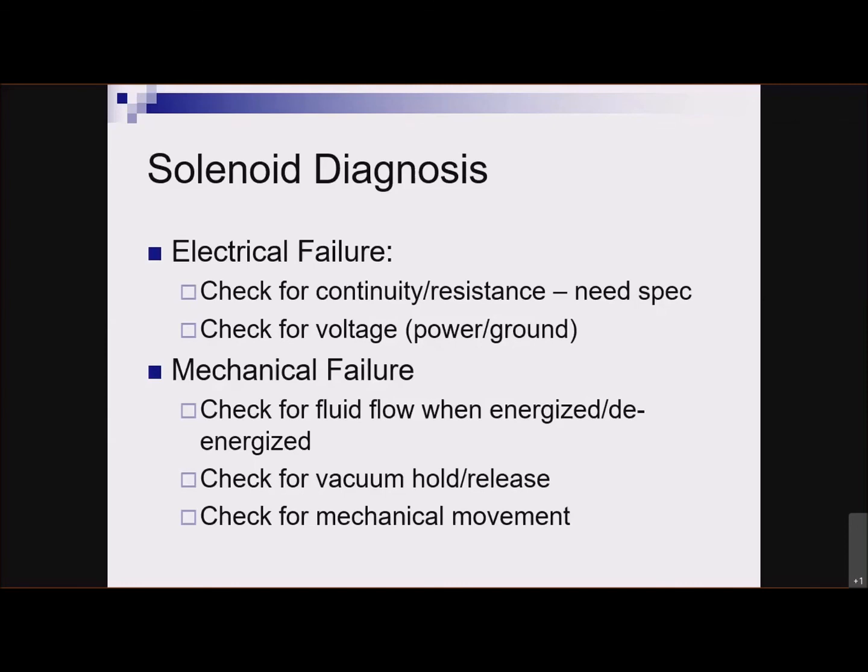As far as mechanical failure, that can be a little more challenging. On a vacuum solenoid, no problem. Blow through it, get a vacuum pump. If it's normally open, then you should be able to get flow through it until you energize it. And if it's normally closed, you should have no flow until you energize it. So if it's a mechanical solenoid, obviously you can just watch it to see if it moves.